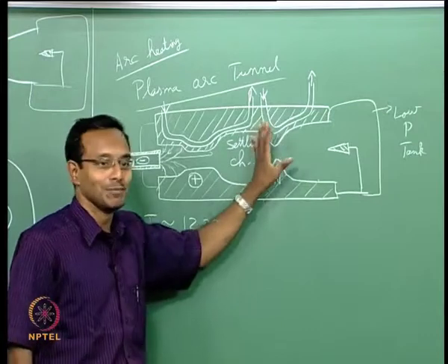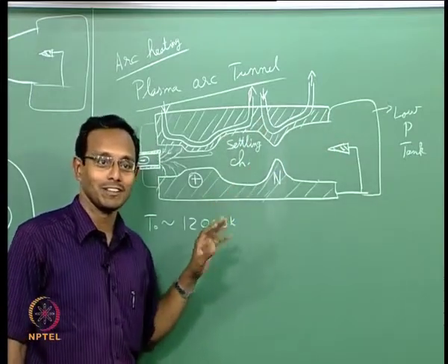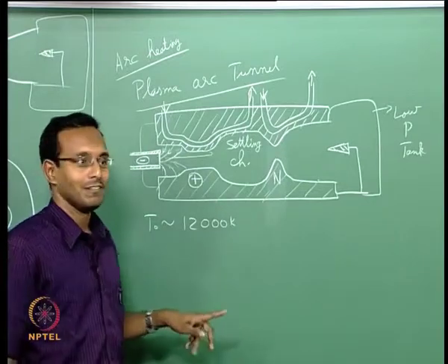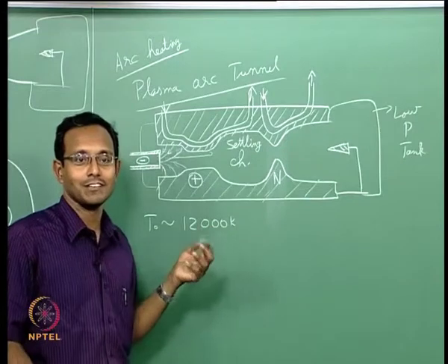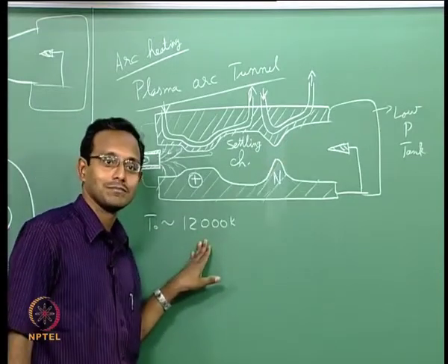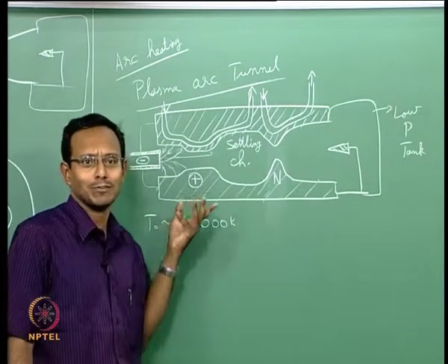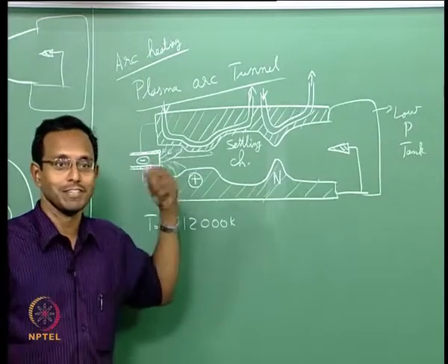This enters the regime of high temperature gas dynamics. Now I have to know a little more than whatever we talked about in our simple gas dynamics course. We need to talk more about high temperature gas dynamics. Why? Because my temperatures are pretty high. I need to think about this. Of course, when I go to Mach 4, the temperature is going to be much lower. It is not going to be 12,000, it probably is going to be 2,000 or so, where I cannot have ions sitting by itself.